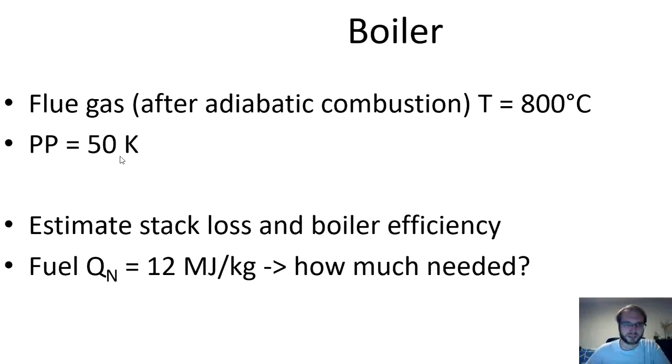This larger temperature difference is because the flue gas, the higher pinch point is required because the gaseous phase has typically much smaller heat transfer coefficient.